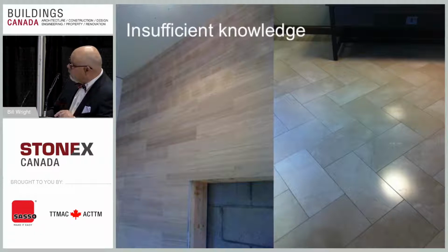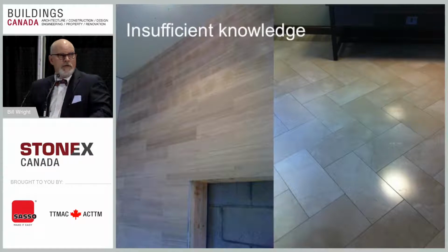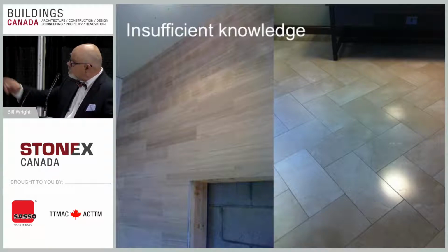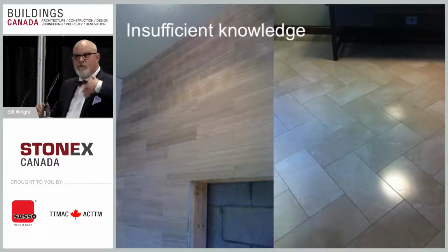And at the far left of that picture is a sliding door that comes across to close it off at night. They must just be ramming that door into that drywall wall with the stone on top of it at night, because it started cracking all the way up and down the wall because the wall was moving, because I said it was on drywall rather than on cement boards.